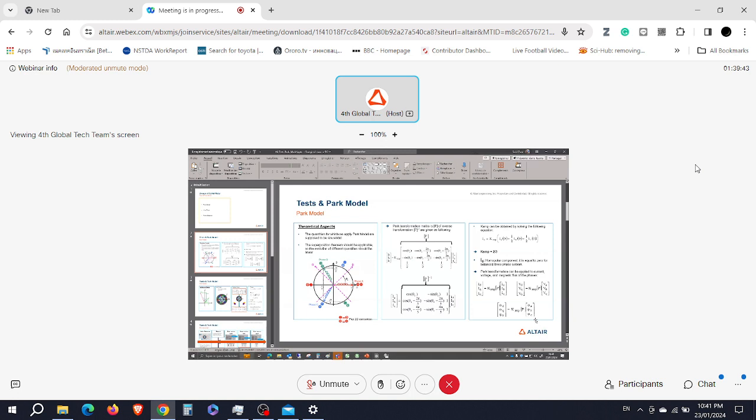So if we know phi, then we can compute the voltages VA, VB, VC, and since the resistance is computed through the analytical formula as well, we are going to impose IA, IB, and IC and vary this current. For each current, we can compute the voltages thanks to the magnetic flux already computed through Flux 2D. Okay, I will come back to this just after.